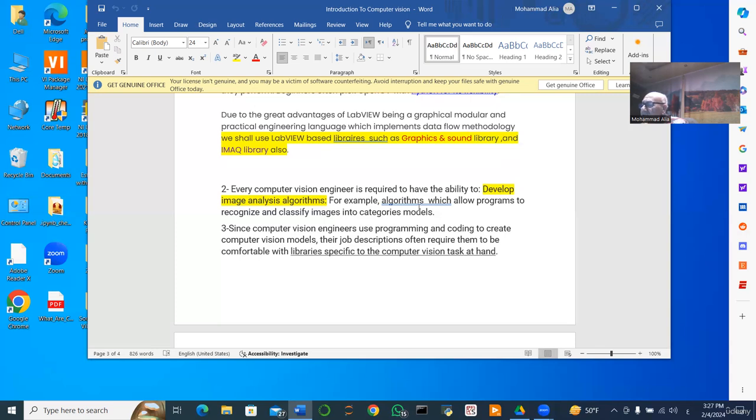For example, when using the vision assistant, you can convert the script to a LabVIEW program, and sometimes you can mix both. So you can have a block of the vision assistant with the already carried out investigations and programming, and you make use of the inputs and outputs and connect it with the external elements to have a LabVIEW program.